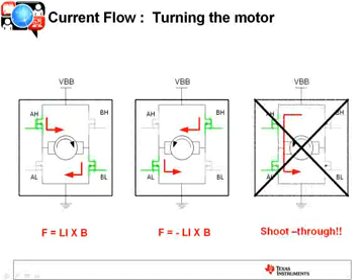And the thing you want to avoid at all costs is shoot through, and that again is where the high side and low side FETs are turned on simultaneously, making a direct short. You're going to blow that driver there. You want to avoid that at all times, and that's where the gate driver circuitry comes in, inserting dead time to ensure that that never occurs.